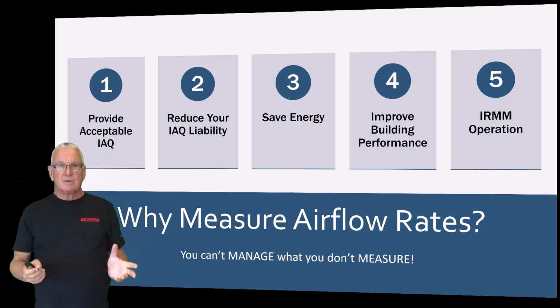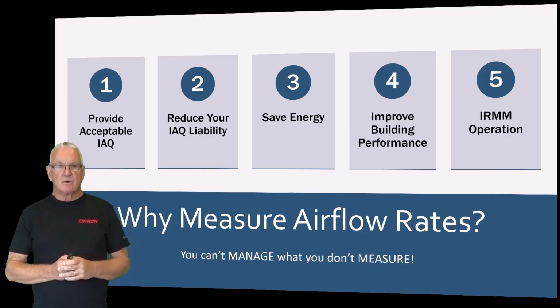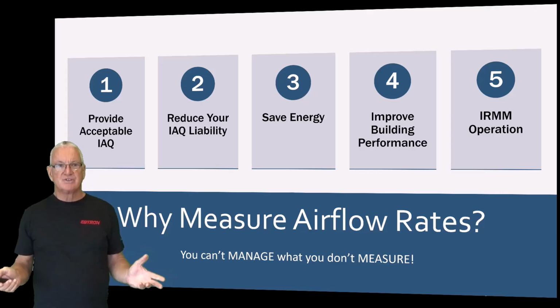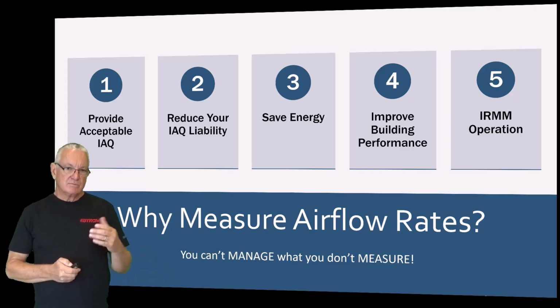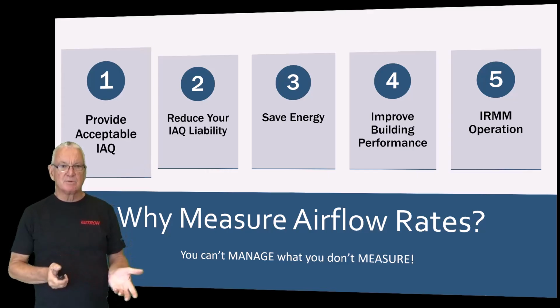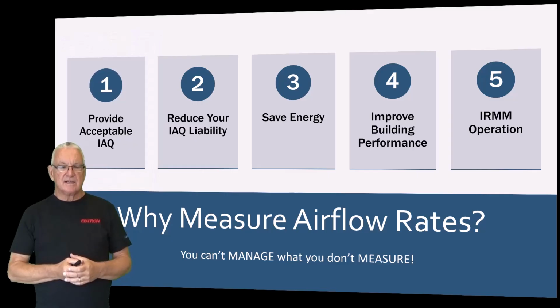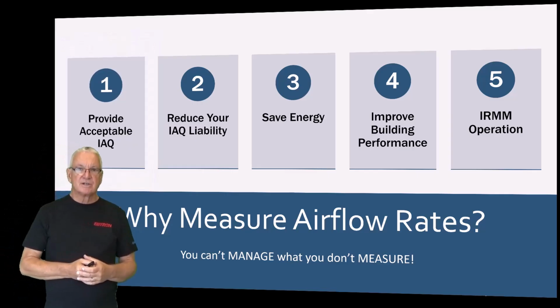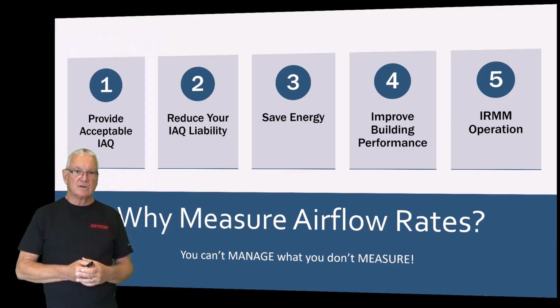Okay, today we're going to talk about a couple things. We're going to start with why measure airflow rates. You can't manage what you don't measure, right? And the major reason for me when it comes to a lot of our facilities is simply to provide acceptable indoor air quality. I think it's very important that you measure airflow rates, and particularly outdoor air, but maybe equivalent clean air. It's also important for building pressurization, which is very important for air quality.